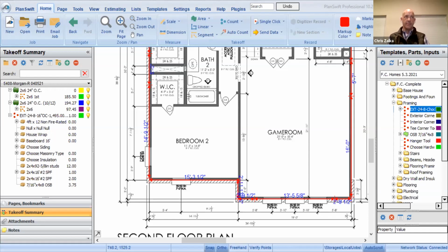Usually, it's a better route if you have your own engineer do your framing plans, and you take your material list to the lumberyard. That's usually because you compare apples to apples. If you have your lumberyard doing your plans for you, like Ed said, if you send it to 20 lumberyards, you get probably 19 different takeoffs.